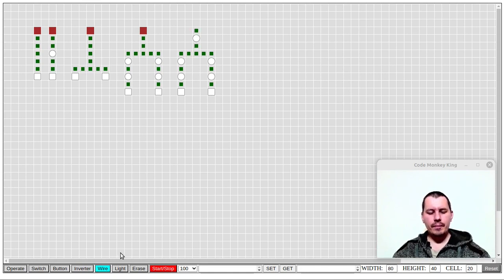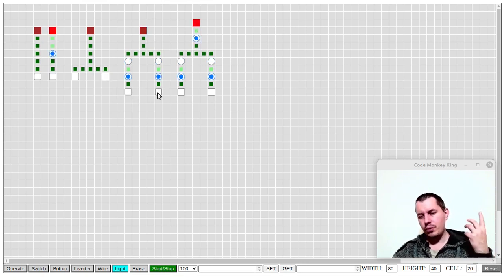The idea is that NOR is OR, but after the result has been achieved, it just inverts the result. That's it. So for instance, if we start the simulation, 0 or 0 is going to be 0, but if you invert this, it would be 1, just like it is here. The same if we do 1 or 0, it would be 1, but inverted it would be 0. Same for this one, 0 or 1, I mean 0 nor 1 to be exact. It just gets inverted again, and here it is also going to be 0. So it just works like OR, but with the inverted signal.